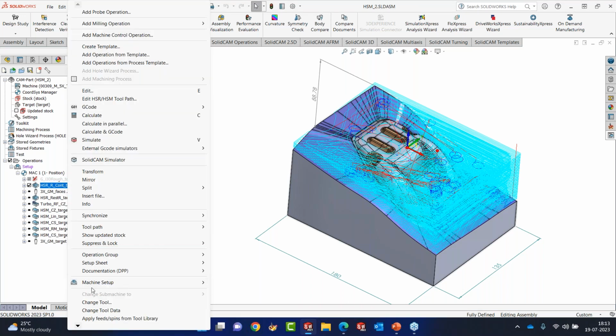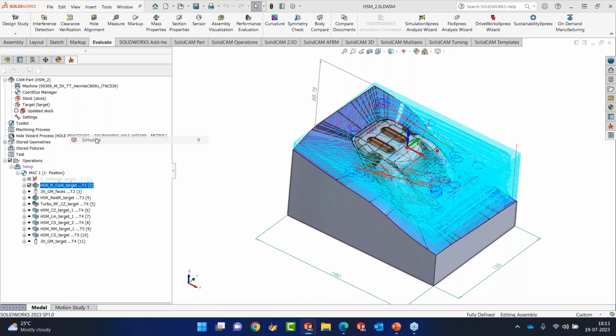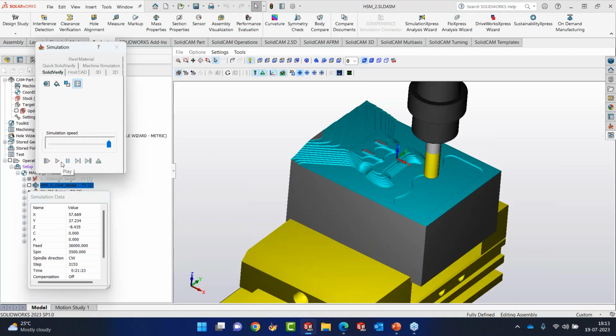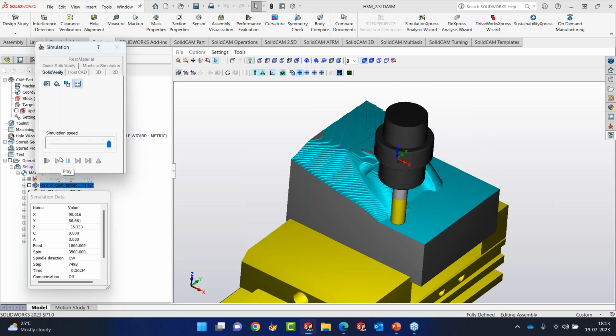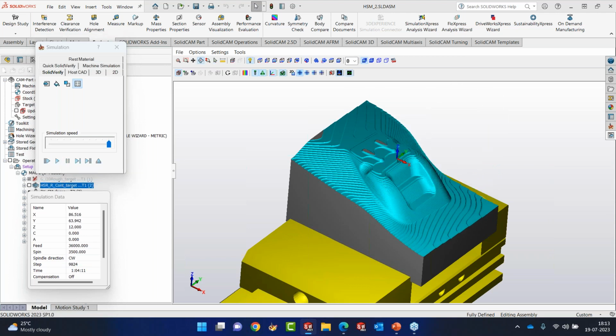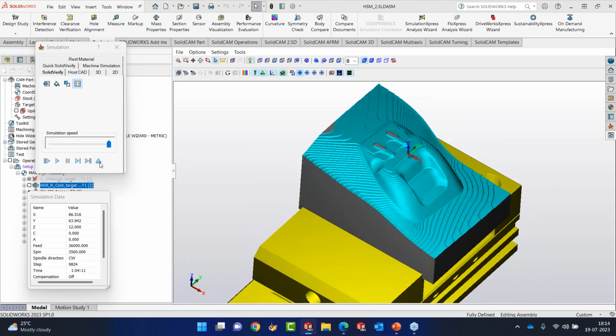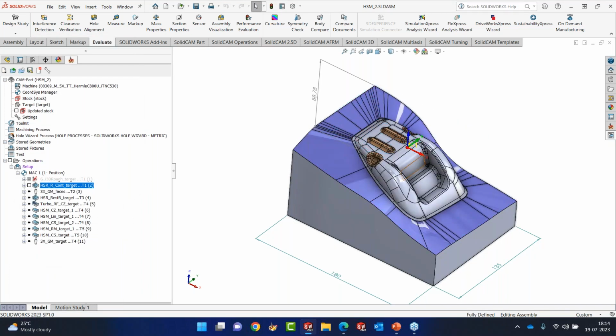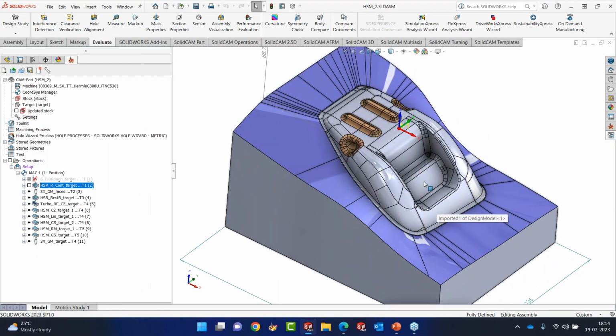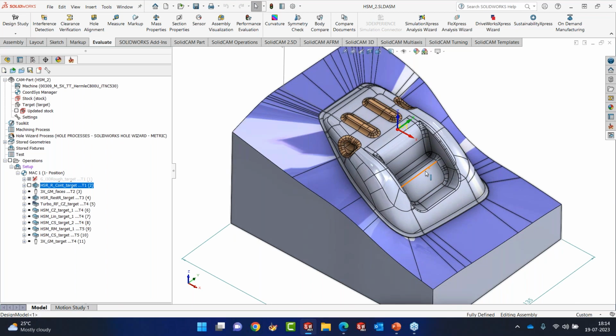So this looks like the traditional pocketing toolpath that goes from top to bottom using small side steps, and this can give you this result. Okay, once we have done the roughing, my next obvious choice would be to go and do rest roughing. But in this case, doing rest roughing, I'm going to waste a lot of time because the rest roughing is also going to go on these surfaces here, which is not essential. It's going to be really a waste of time.